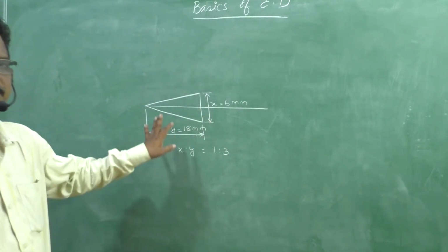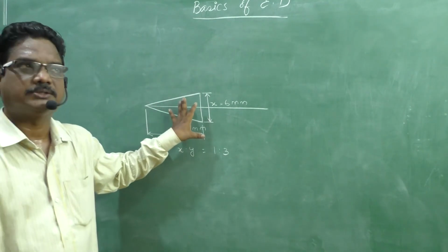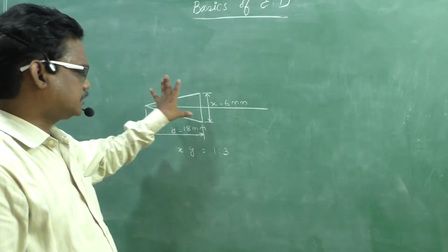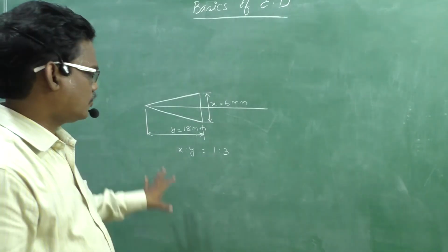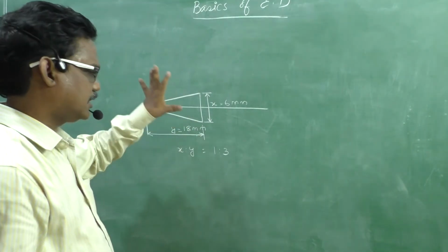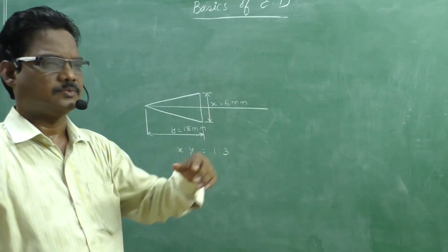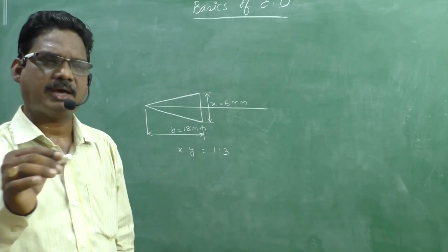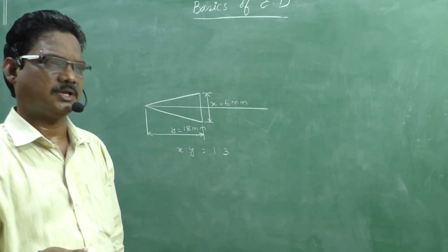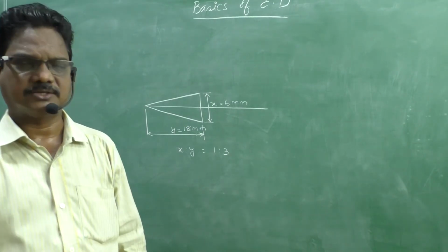With that proportion, first you need to draw the arrowhead. Once you draw it, you can observe the shape. Then you can remember that shape without taking the dimensions every time. You can draw the arrowheads for the dimensioning directly in the drawing sheet.